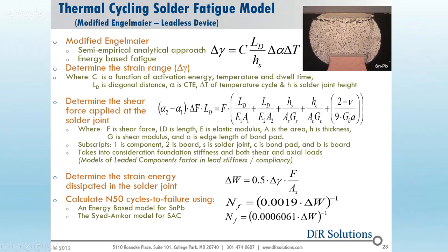So this is the difference in temperature from low to high, as well as the difference in thermal expansion coefficient. Plug the rest of the information in, and we get a force that we calculate from this equation. So this is a purely analytical approach of looking at solder fatigue.